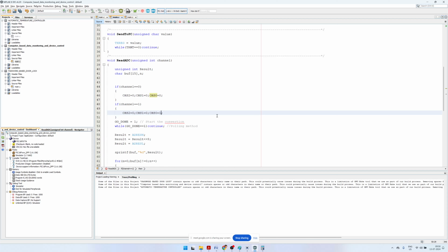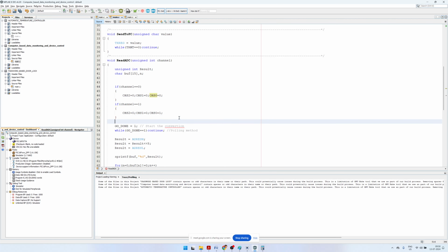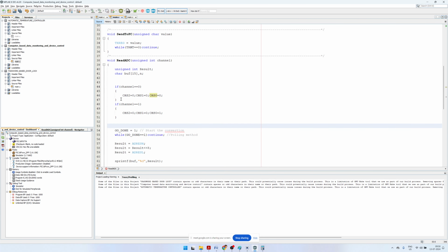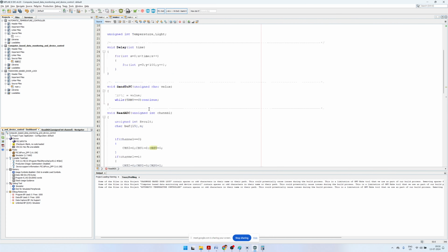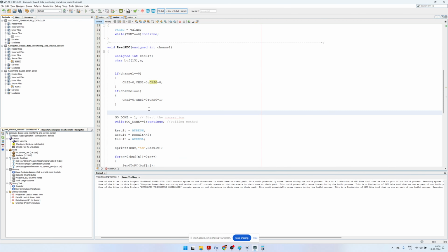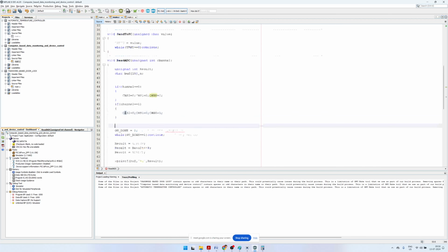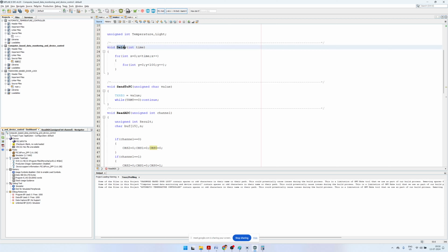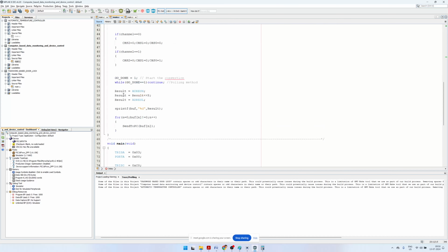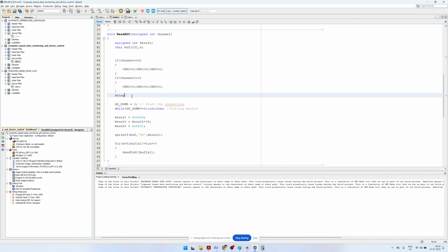Okay, done. Then it is a practice that after channel selection you need to provide a little time for the ADC to get the channel properly selected. For that I am putting a very minimal delay of maybe 2 millisecond time. A 2 millisecond delay, then I will tell the ADC to convert.